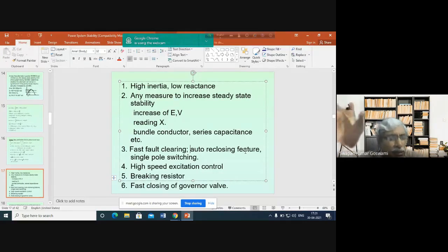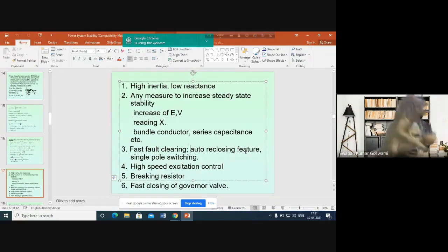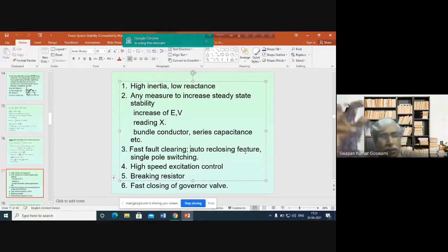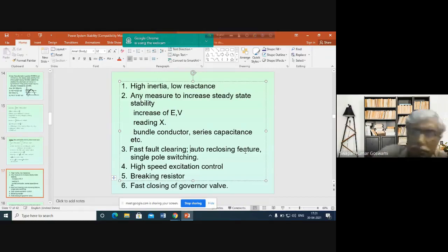Now the circuit breaker is getting a signal from the relay. As the circuit breaker observes that a fault has occurred, as signalled by the relay, it will open the terminal of the transmission line. So the transmission line will be disconnected. Now the current or the power coming out of the generator will get no path to flow through the transmission line because this line is not there. Then it will try to flow through some other path, if there are other transmission lines.